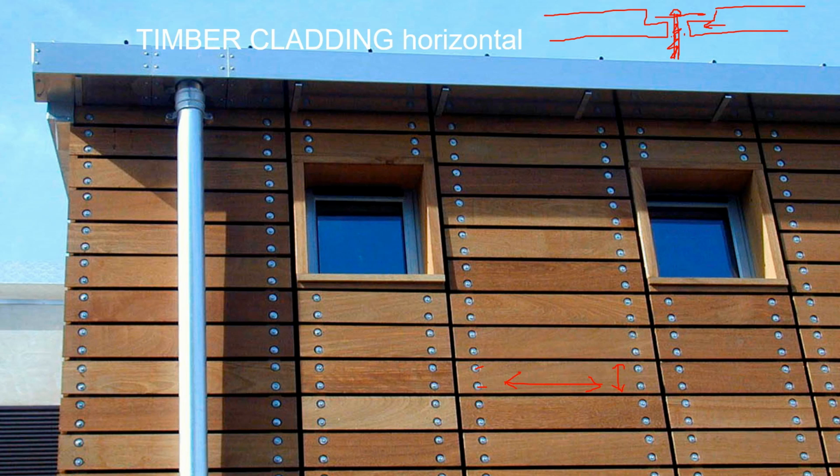The other thing about this image, which is quite interesting, is the windows here. So the size of the windows have been sized to work in with the cladding. So we can see that there are 4 boards for the height, and there's a vertical gap that lines through here. So the windows have been thought about at the same time as the cladding. So it's not a mistake. It's not just a CAD drawing that's been put together. So you need to consider what the outside appearance is and how the cladding is going to fit in to make sure that you can design your windows to be in keeping with the rest of the facade.